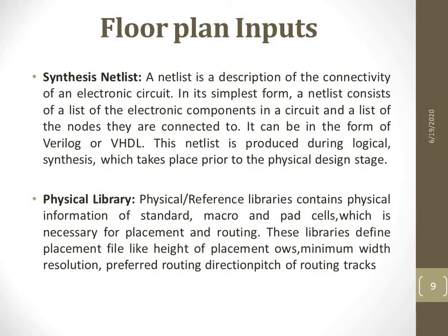Suppose I design an XOR gate, and the synthesis tool says that there is only a need of one logic gate, that too an XOR gate with 2 input nodes and 1 output node. That means how many elements are noted down in the list? The list has 2 input nodes, 1 output node and 1 logic component.